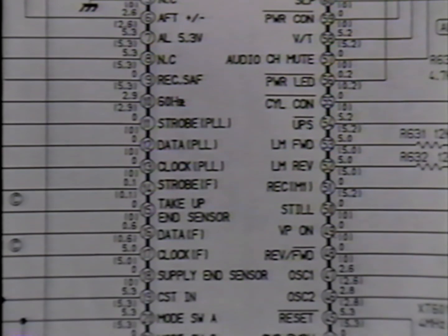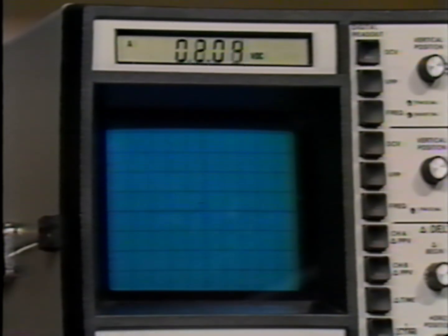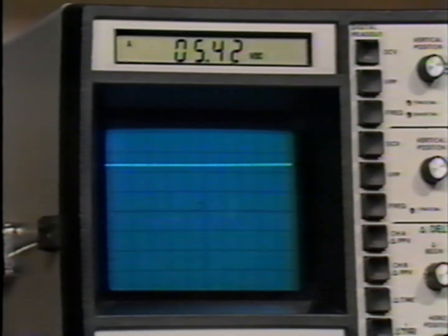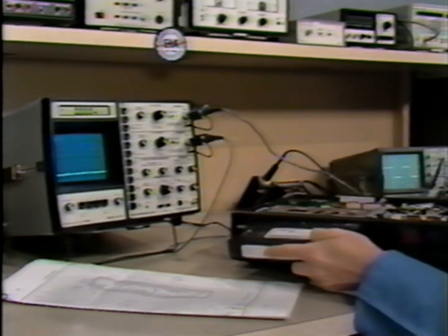Just as single-bit inputs provide much useful information, the microprocessor can perform much of its control function through single-bit outputs. In the VCR, such functions as on-off control of the loading motor, the cylinder motor, and the capstan motor are easily performed through output lines. Proper operation of these output lines can be determined by simply monitoring them with the logic probe or oscilloscope during operation. When observing these lines, be sure to put the unit in the operating mode that will activate the line under test.